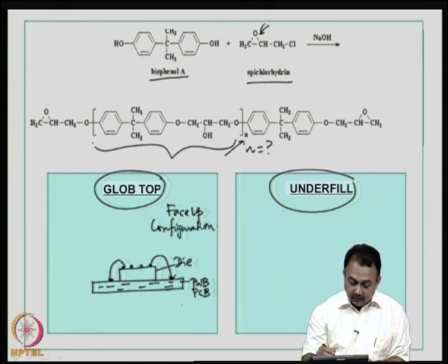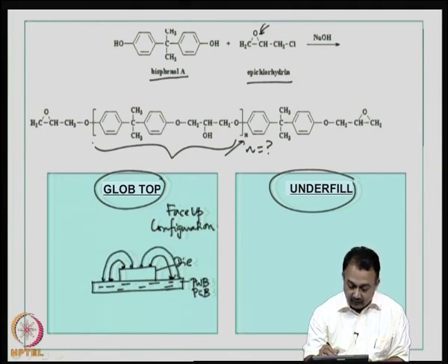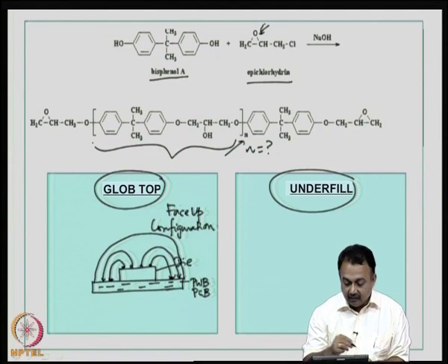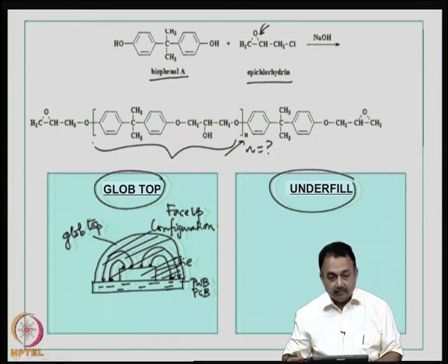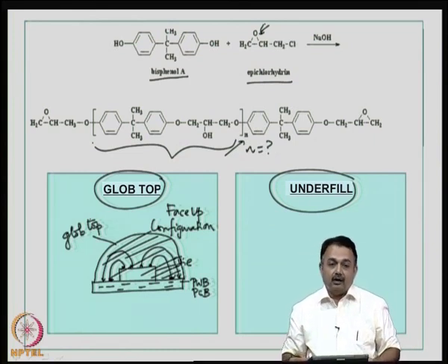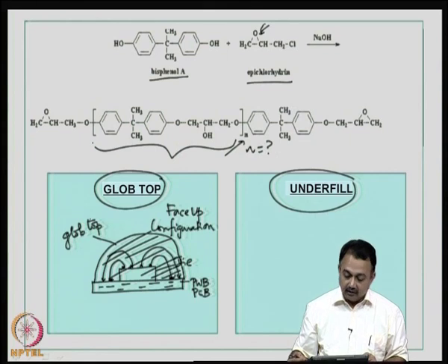Okay. So, similarly for other wire bonds you will be doing the connections. Now, you apply, using a syringe or some other dispenser, this epoxy resin and cover the entire wire bond structure that you have generated. So, this is a protected area. This is known as glob top. I hope you are clear with this explanation about when to use a glob top configuration of epoxy resin.